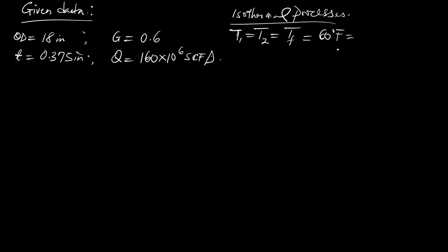We have to convert this to Rankine, which is 60 plus 460, giving 520 degrees Rankine, because we are supposed to use absolute temperature and absolute pressure.